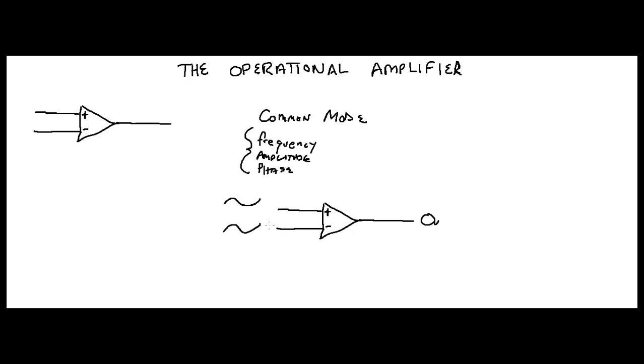There is a specification with the four letters CMRR. It stands for Common Mode Rejection Ratio. Basically, you want to have the common mode amplification very low, while you want to have the open loop gain of your amplifier very high.